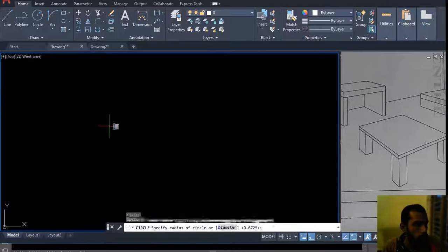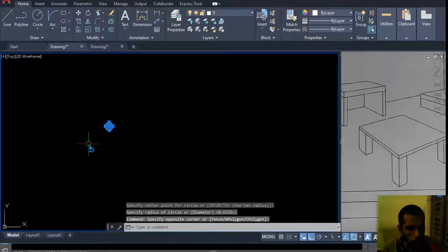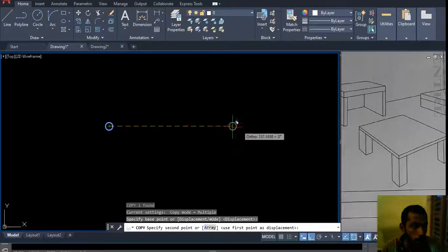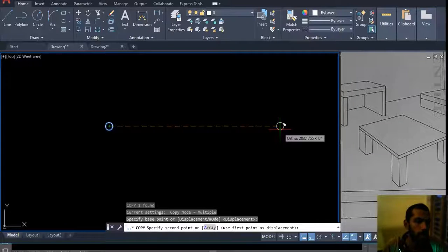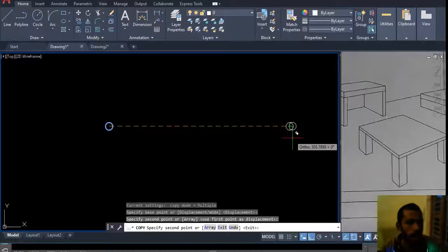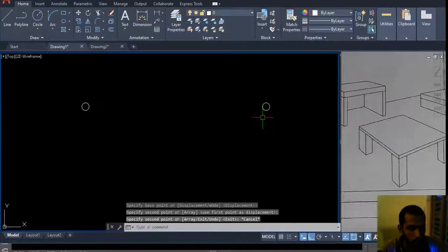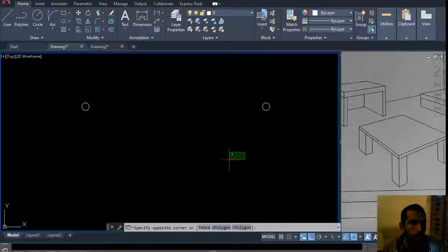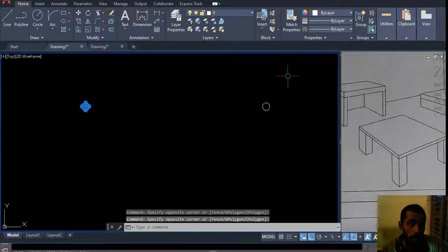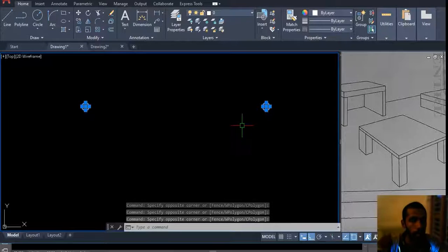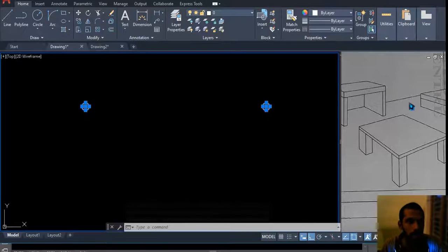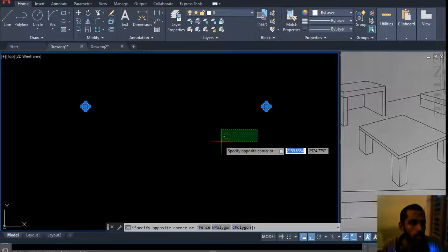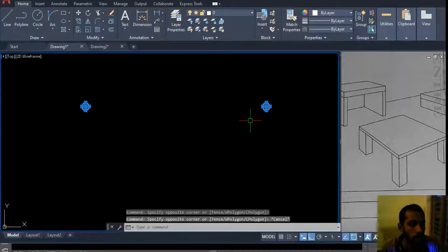So first vanishing point here, and you have to make sure that you put an exact copy of the first line, turn on ortho and move right into here. The distance between these points is not really important. First step is to pick 2 vanishing points there. Okay, once you fix the position of the vanishing point, please do not move it. That's very important. If you moved it, the perspectives might look different, so please do not move it once you have placed it.